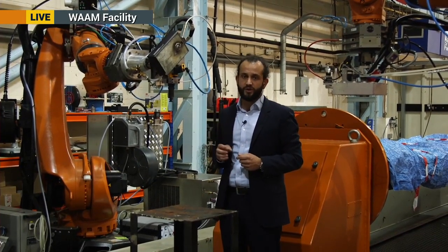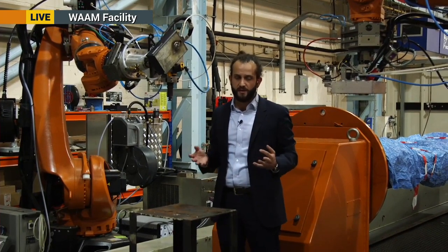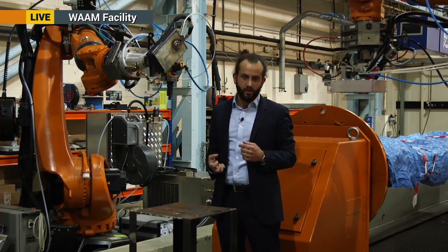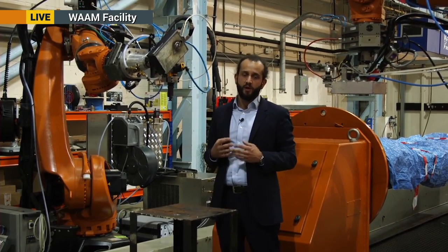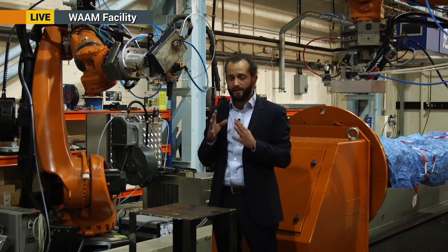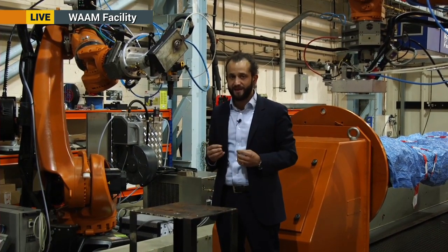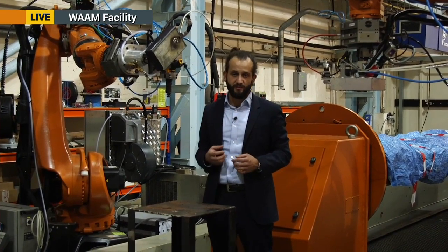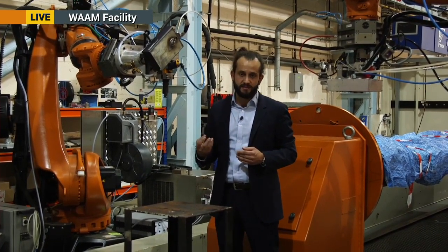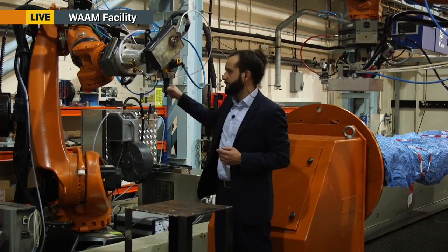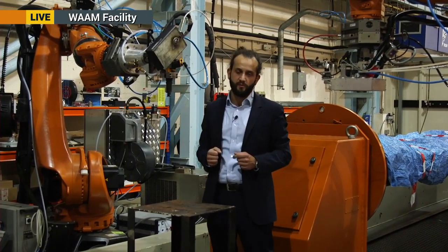So at the moment we have actually proven that for a wide range of alloys like maraging steel, Inconel 718 or titanium 6-4, we can produce properties that are comparable, if not better, than the equivalent forged alloy. At the core of this is the baseline excellent structural integrity that we have. As I said, wire is clean and normally yields structures that are 100% dense. So even without the mechanical treatment, we've got a very good starting point to begin with.